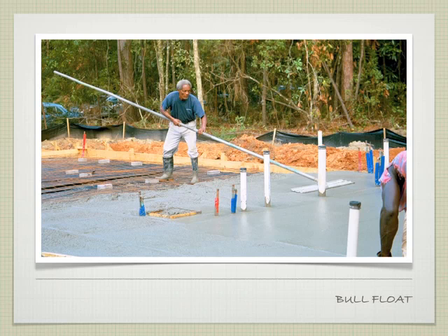And you can see the difference between the rough concrete that hasn't been finished yet, or hasn't had its initial floating, and the concrete that has had its first set of floating. Notice that there are still little gaps, little things that aren't quite perfect yet. And notice also that it's incredibly hard to finish around all of the plumbing and the other things that poke up through the slab.